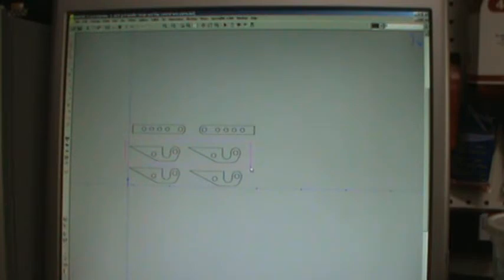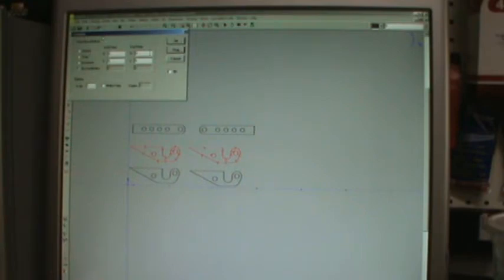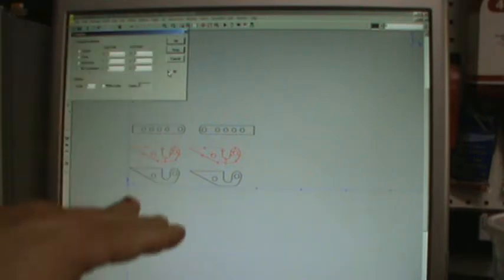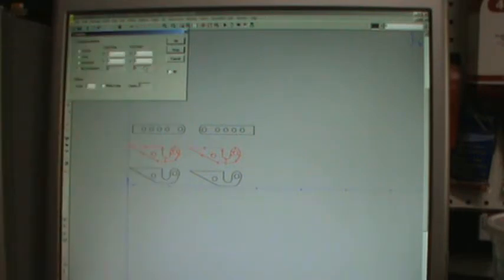I would like just a little bit more clearance, so I'm going to highlight those, come back up here to change once again, then translate. But at this point in time, instead of saying drag, I'm going to use the translation method up here, and it gives you little boxes that you can select in. We're going to do by coordinates. 3D is not checked. See, if you click 3D, it actually allows you to vary its height in the Z-axis, but we don't want to do that.